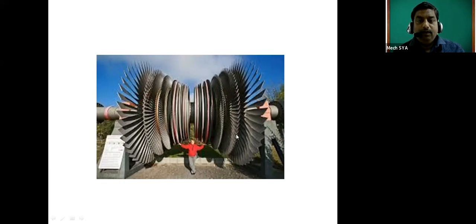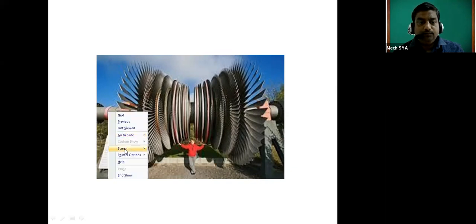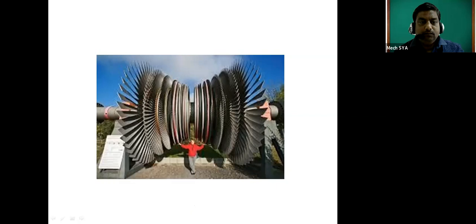Now some are the moving blades. Those blades are moving. Some blades are attached to the stator. Moving blades are directly mounted on the rotor. This is the rotor, we can call it a rotor here, shaft. Some blades, moving blades, are attached on this particular rotor, and fixed blades are connected only to the casing. So this is one of the pictorial views of the wheel. So this is compact: fixed blade, moving blade, and steam is impacting on the blades. It is impacting in a tangential direction.